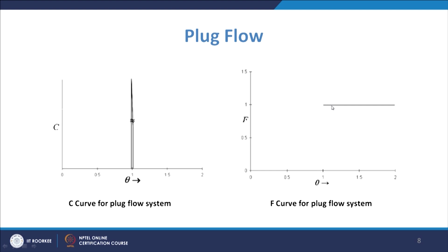So, basically tracer is continuously being put in, and all the tracer is flowing. It will stay together in the tundish for the theoretical mean residence time period, and after that they will start exiting. Once they start exiting, the concentration will directly reach, not gradually increase. They are all coming out, so the dimensionless concentration is 1 itself.